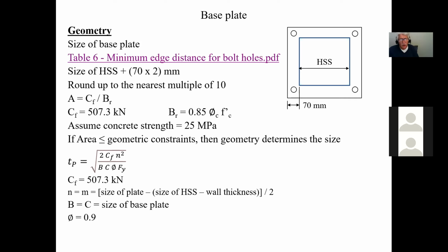I start with my geometric constraints, and then I fix certain variables. I take the textbook solution to solve for eccentrically loaded plates, and I already start eliminating some of the variables, and I'll explain that next week or the week after when we do the exterior columns and the exterior base plates and so on. Okay, so that's it. So you're going to have to do that, and once you size this and everything is good, you're already ready to do one of the details on your steel drawing.